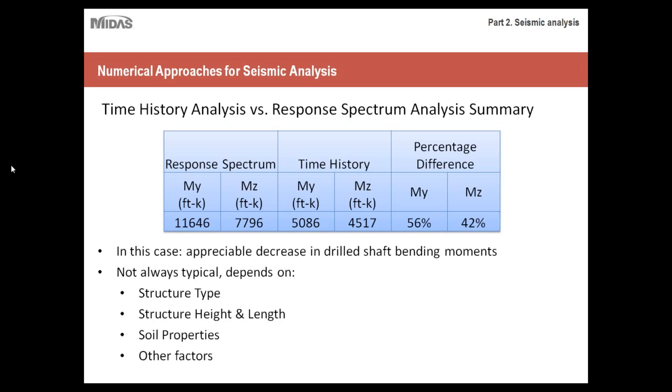So I'll just review that quick point that I made. With response spectrum analysis, the results will be more conservative because you're making more assumptions and you're taking fewer variables into account. Whereas with time history analysis, it takes longer to do because the level of analysis is higher. There are more variables taken into account. It's less conservative and it's more optimized. So there's that trade-off. Once again, which type of analysis you would run depends on the type of region you're working in as well as the scope of your project. But just keep that principle in mind.